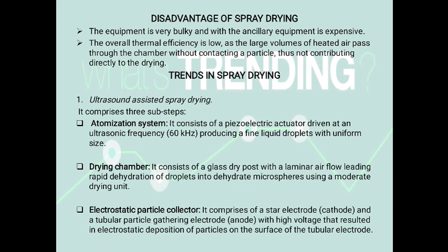In spray drying, the equipment is very bulky and, with the ancillary equipment, is expensive. The overall thermal efficiency is low as the large volumes of heated air pass through the chamber without contacting a particle, thus not contributing directly to the drying.